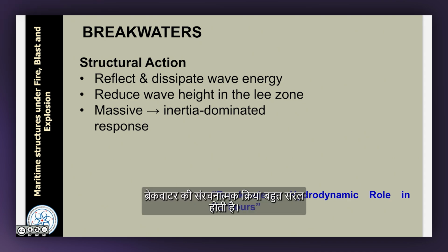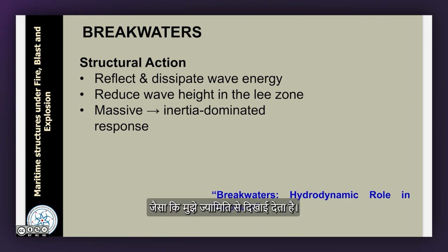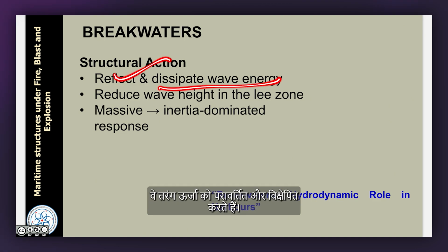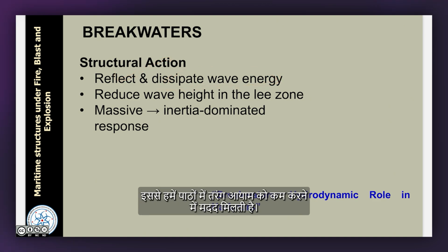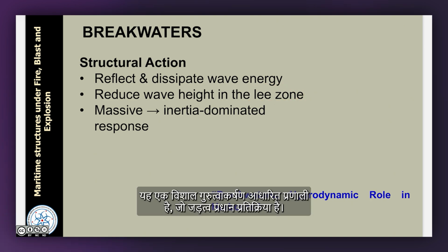The structural action of breakwaters is very simple, as I see from the geometry. They reflect and dissipate wave energy. It helps us reduce the wave amplitude on the lee zones. It is a massive gravity based system which is an inertia dominated response.